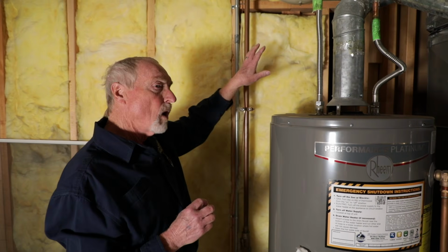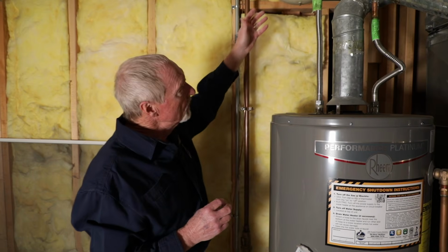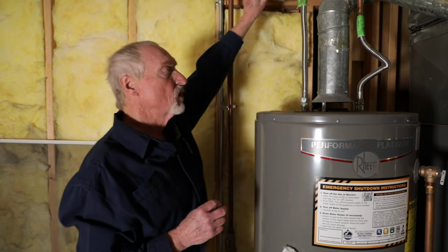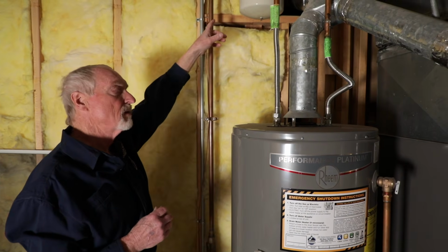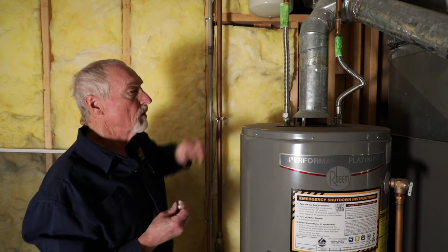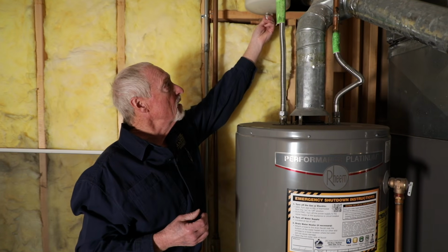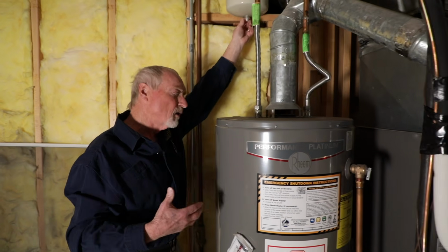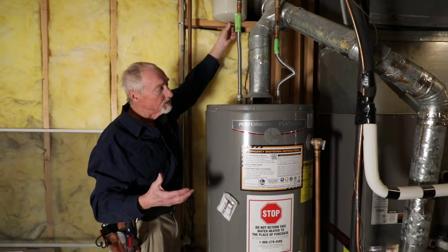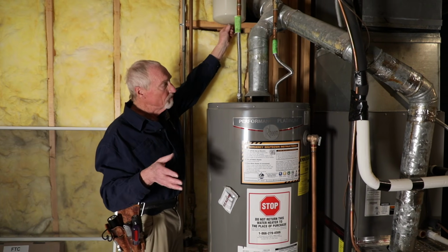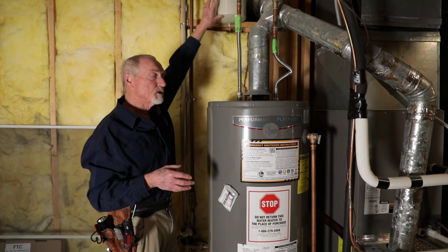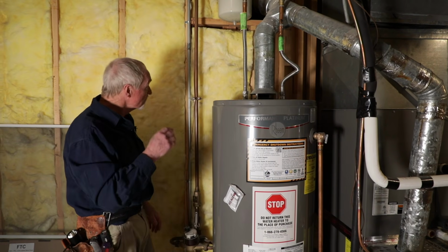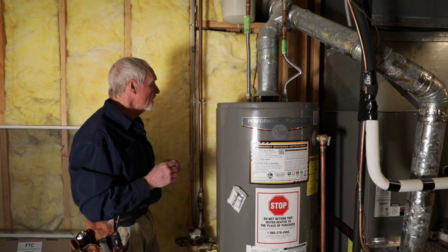If it sprays me with water and air, I'm thinking maybe I just have a little condensation in here or something, not a problem. But if it just sprays me with pure water, I'm thinking the diaphragm in here has failed and we need to replace this. I don't check it for air pressure because that would require me turning off the water to the house, draining the house down, and then checking it. But for your information, normally this is inflated by the plumber to the same water pressure as the house. So this looks good here.